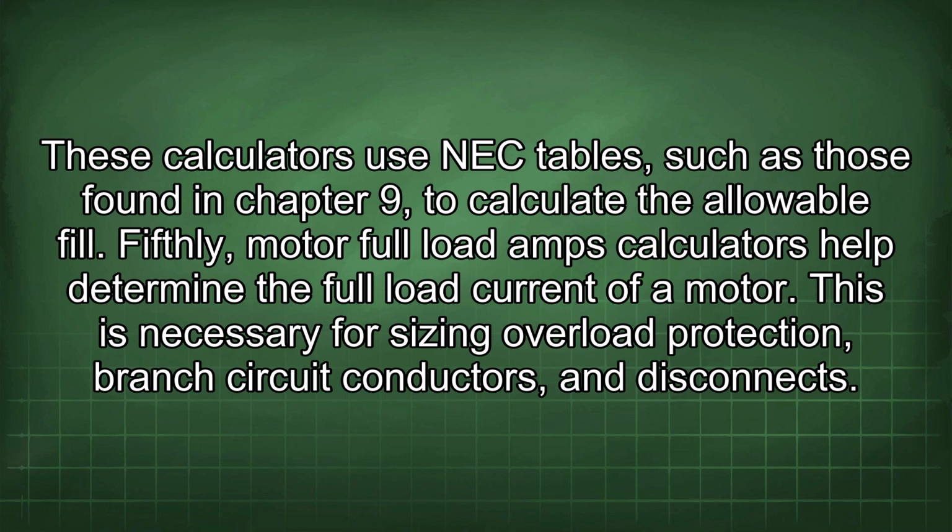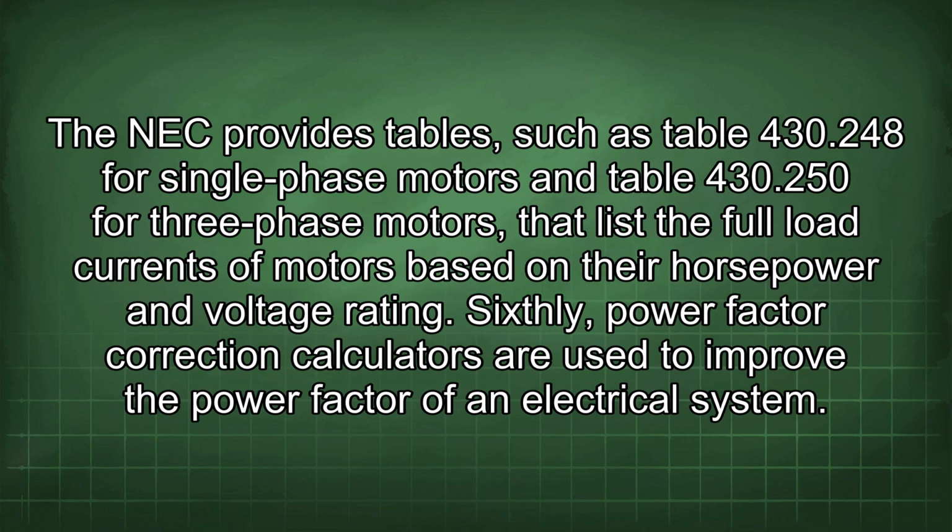Fifthly, motor full load amps calculators help determine the full load current of a motor. This is necessary for sizing of load protection, branch circuit conductors, and disconnects. The NEC provides tables such as Table 430.248 for single-phase motors and Table 430.250 for three-phase motors that list the full load currents of motors based on their horsepower and voltage rating.